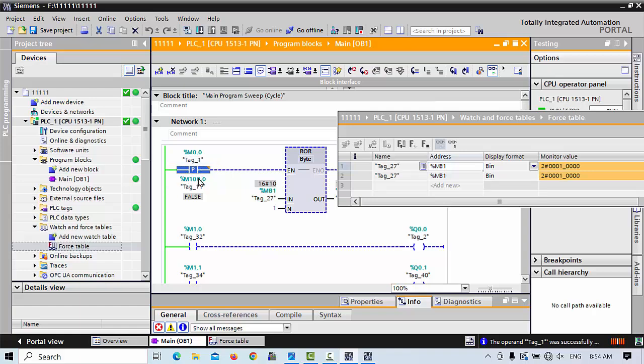Also you can use it here, any signal from outside. For example, in the field when you're using this command, maybe one sensor is sensing for your bottles, for 250 ml bottles. There are many types of bottles, different in size, for filling water or filling juices or something. When you put the signal, one signal you can put for this one, signal M0.0 or I0.0 when you write it here. And from the field comes the signal I0.0, you can use the one signal for 200 ml, 250 ml bottle.